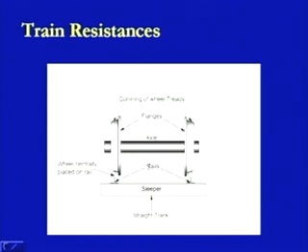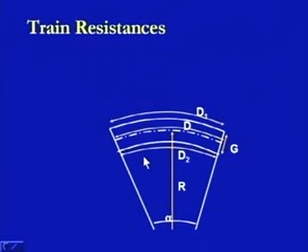And this type of differentiation between the straight track and the curved track is going to be used for computation of the resistance. The same thing here is being depicted in form of the movements or the distances which need to be covered here. Here this is a curve which is being shown in this direction. This is the outer rail and this is the inner rail. There is an angle alpha of this curve and radius R, that is the radius R corresponds to the central point of this curve, and it is being read at any gauge G.